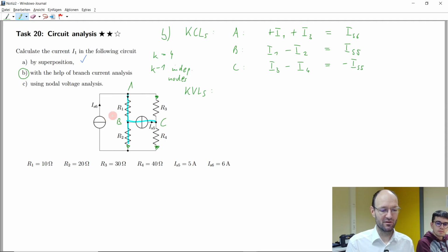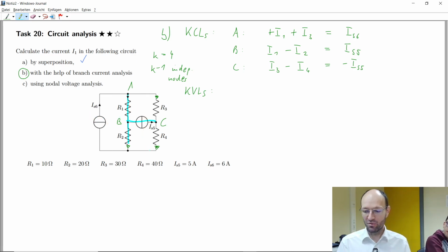And in this case, we would get 1, 2, 3 more Kirchhoff's voltage laws. And we could write them down, and at the end we would get a system of 6 equations for 6 unknowns: our 4 currents and the 2 voltage drops across the current sources. And so now things are getting not complicated, but you also have alternative ways. And one rule that is written somewhere in textbooks says, okay, this complete tree should not go over a current source.